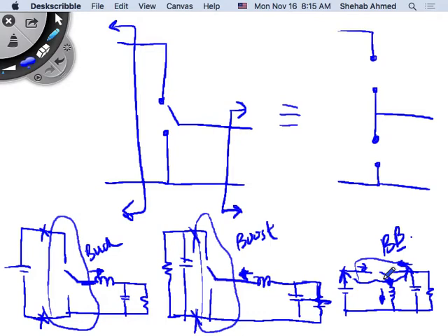So all transformers, what they do is transfer power from high voltage low current to what? Low voltage high current, for example. They maintain power with some losses in the middle, but they change the condition of the voltage and current. That's what they do, and that's what the power converter does. And for the switch mode power supply to do that, it takes energy from the source, stores it in reactive elements, then takes that energy stored in a reactive element and dumps it in an output reactive element, for example. That's what we saw happening in most cases.